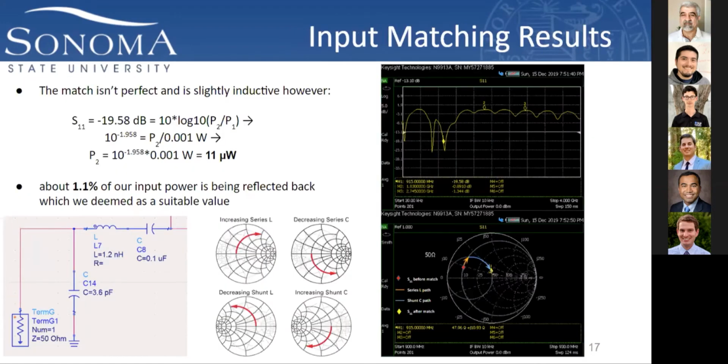For the matching networks, I decided to focus on using a low-pass filter configuration, in an attempt to filter out frequencies that are greater than our 950 megahertz signal, such as harmonics. To find the correct matching network, I began by adding components to the amp in a low-pass filter configuration and then measured the S11 values.